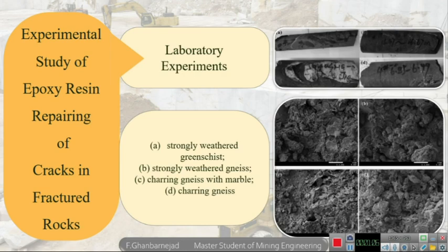The uniaxial compressive tests are carried out by the MTS 815 rock and concrete test system. The density, porosity, and uniaxial compressive strength are determined for the epoxy repaired rocks. These parameters are the important indexes of the mechanical properties of rocks. Because the fractured rock in the shear zone has four typical types, the experimental tests are carried out for each type separately.